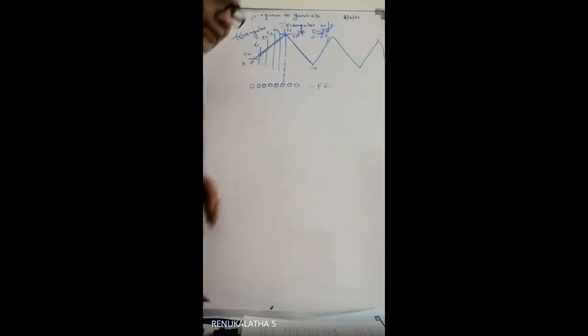It was a square waveform in the other example, so it had only 2 levels. We sent 0, we called a delay, and suddenly it went to 1, and it was generating a high level for a certain interval of time. As long as you send FF, it will be generating the high level value. So here it is not like that. In between, we have different ranges of values of amplitude. Initially we know that we need to send 0, because it will start with 0 amplitude.